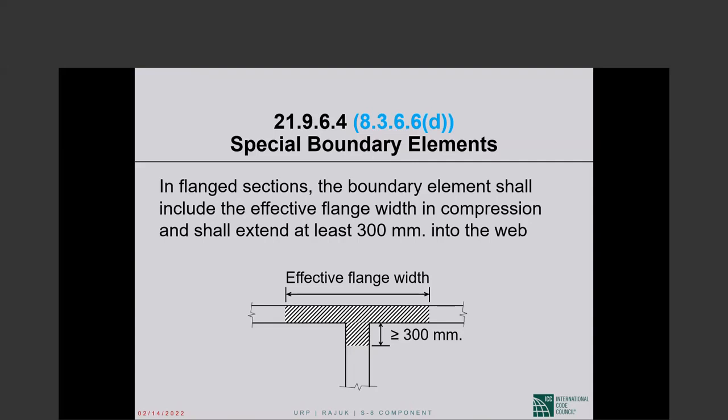I think that by transverse reinforcement, he must mean the horizontal shear reinforcement. If that requires lapping, you just lap them somewhere near the middle.